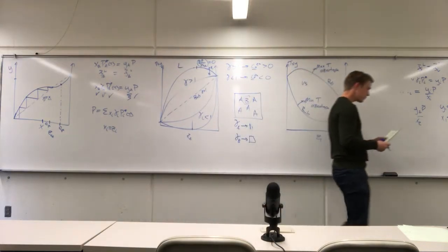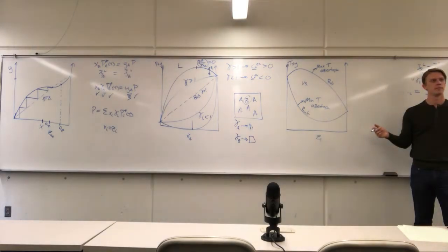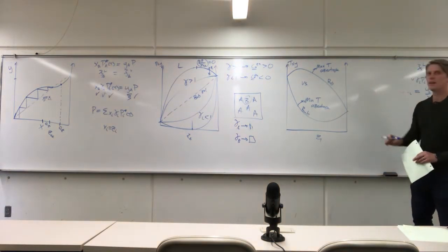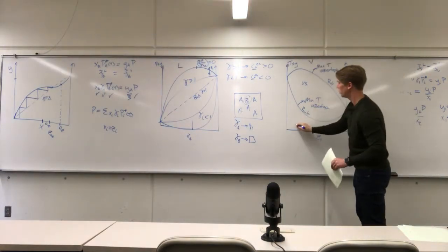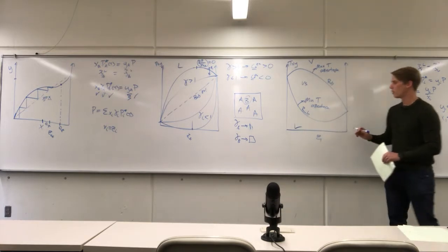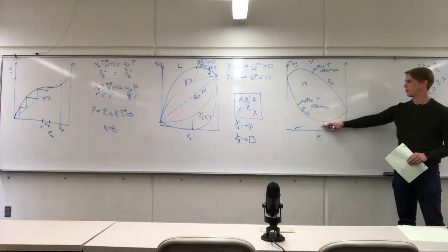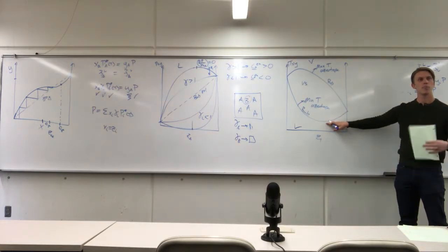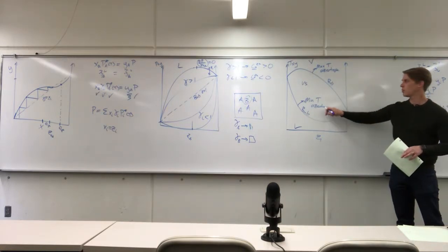So, which of these two is more common? Let's not answer it. Let's walk it through step by step. High temperature, what phase are you in? Vapor. Low temperature? Liquid. Okay. So I'm a liquid, and I'm getting heated up. So the first one that I encounter here would be potentially a minimum temperature azeotrope. So that means I'm boiling at a lower temperature than I would normally do if I were an ideal mixture. So this one's going to be more common.